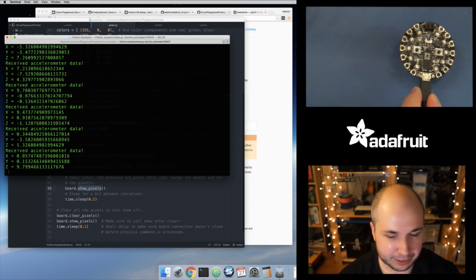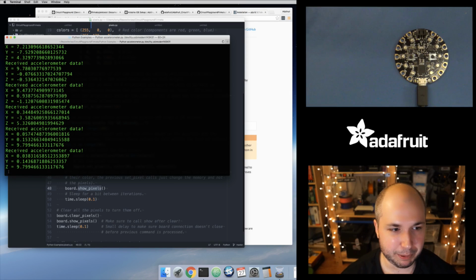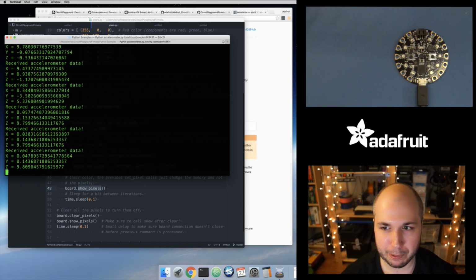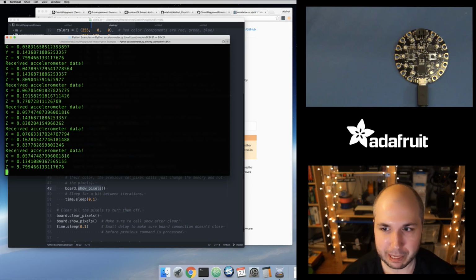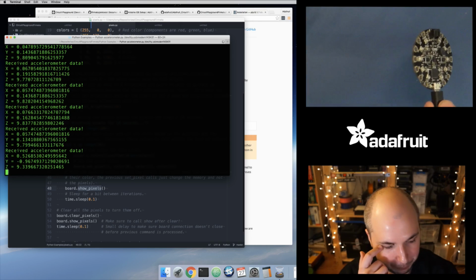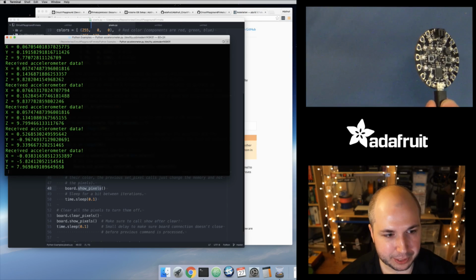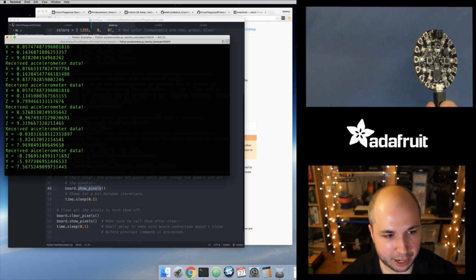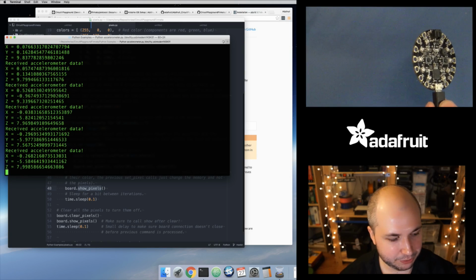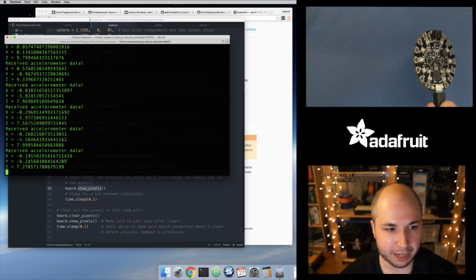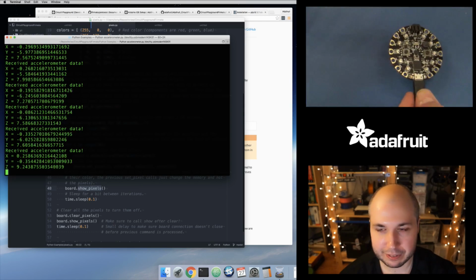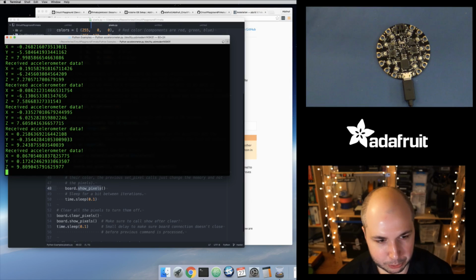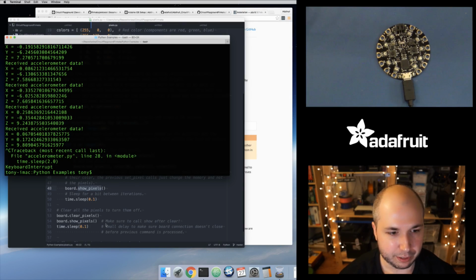I mean, you can do a lot of neat things with an accelerometer, and they're typically kind of scary components because there's a lot of math involved sometimes, as you get into 3D things like this. But just doing basic stuff, even if you want to detect like, is it at a 45-degree angle, you can check and see like, okay, now my z-axis is a little bit less than 9.8 because it's not getting the full force of gravity, and now my y-axis has a little bit of force going that way. So you can even detect little things like that. So that's cool. So that'll print every 2 seconds the value.